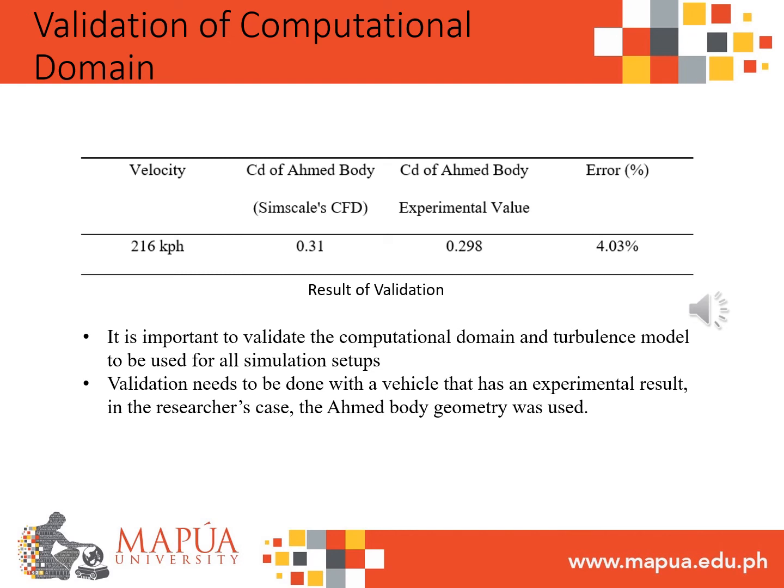In the methodology of this study, it is stated that we need to validate the computational domain and the turbulence model we will use with our simulation setup. The validation will be done with a model that has an experimental result. In our case, we will use the Ahmed body geometry. Based on what we see from different studies, this model is usually used for validation purposes.